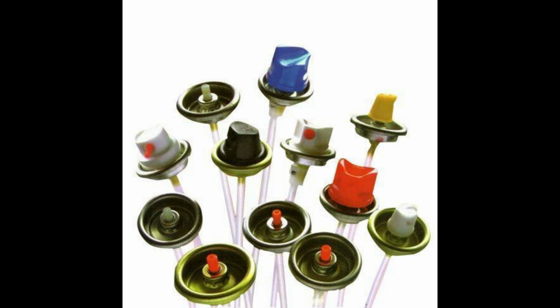Aerosol valves leverage pressure between two fluids to force product through an atomizer, creating a useful fine mist. This is done by filling the can, tank, reservoir or container with two different fluids. The first is a high pressure propellant of lower density, and the second is the desired product to be dispensed. The high pressure propellant pushes up on the stem and mounting gasket, keeping the system sealed while also pushing down on the product.